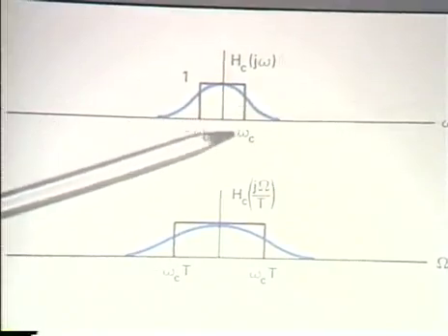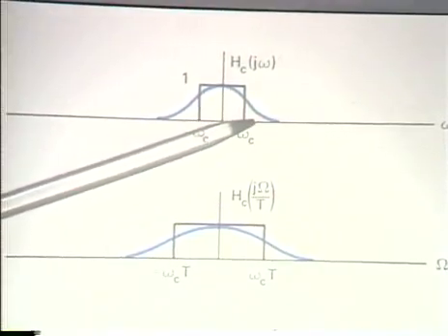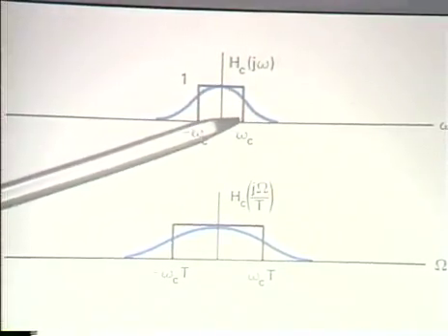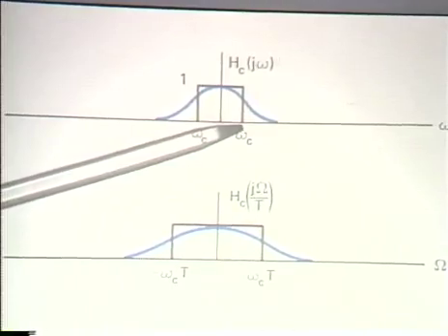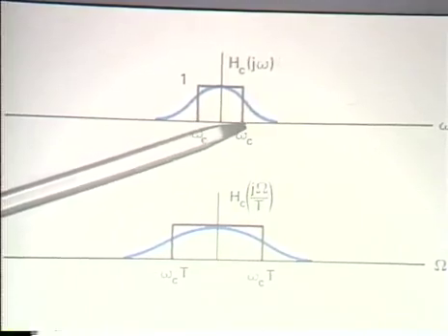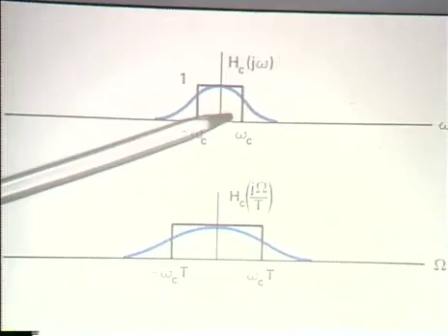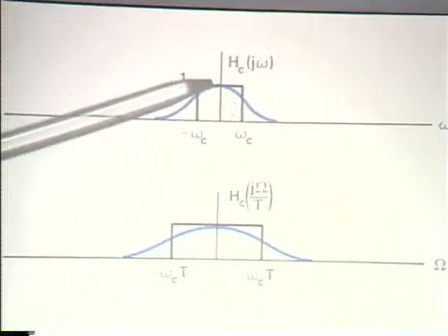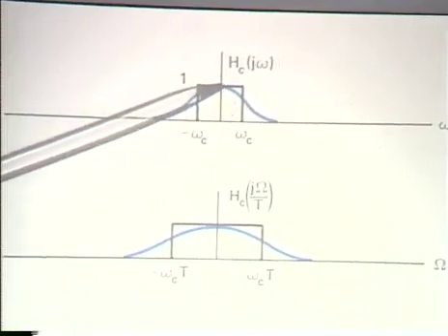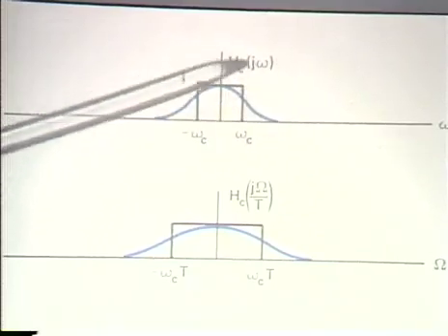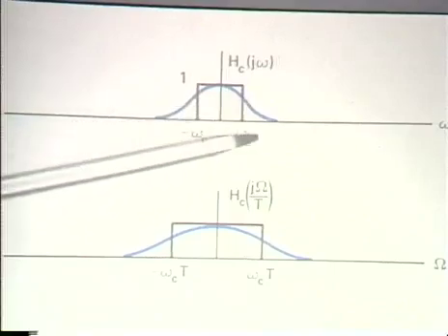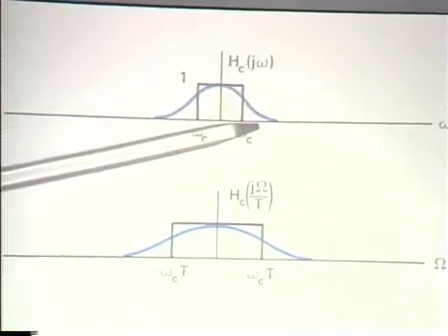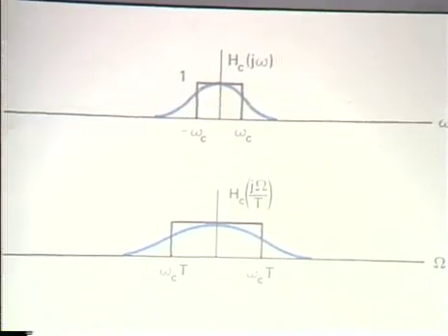And in particular, now, if we were to simply pick that parameter in the impulse invariant design, capital T, as equal to unity, and I indicated just a minute ago that we can pick it arbitrarily. If I pick it as unity, then the procedure would consist of designing the continuous time Butterworth filter meeting or exceeding the appropriate specifications and then going through the impulse invariant procedure.